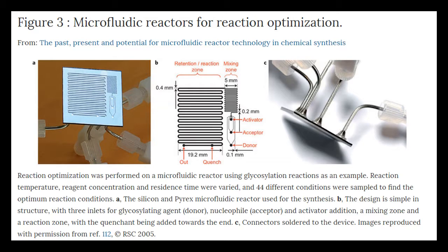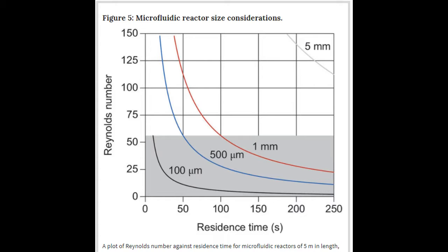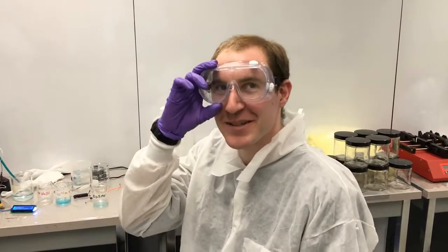The Reynolds number accounts for characteristics of both the fluid, which are density and dynamic viscosity, and the environment in which the fluid is manipulated, such as fluid velocity and characteristic dimension. We had two good indicators for the characteristics of our fluid and also for the environment of our 3D reactor design. For the characteristics of the fluid, we used the Reynolds number, which was indirectly calculated using the Péclet number, which was calculated using the spectrophotometer by Arduino.